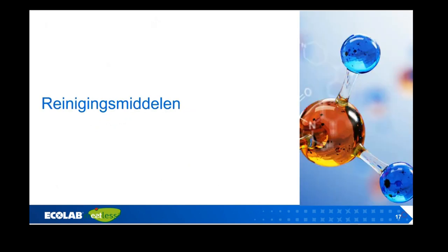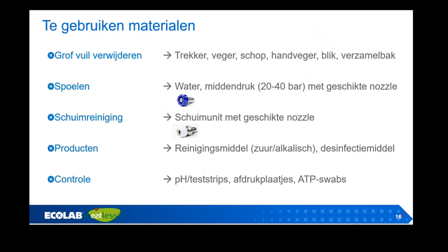But you need to check it, because you don't want to have a residue of your product still on the surface. That's the pH check. We also have hydrogen peroxide test strips, so you can test if there's still chemical on your surface. We call it a residue tester.